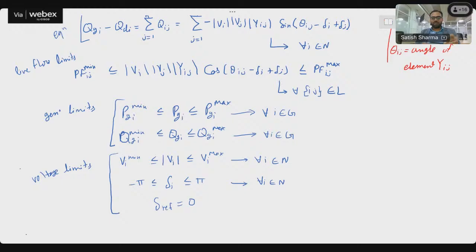So earlier today, we learned how to use the fmincon function for DCOPF. So we are going to use the same function for ACOPF as well. But let's first of all check whether it is linear or non-linear. If I look at the very last equation, it is quite obvious that this is only an equality constraint, so it is linear.